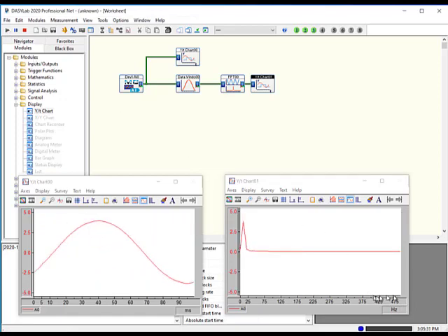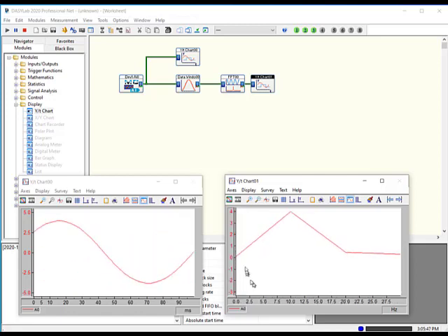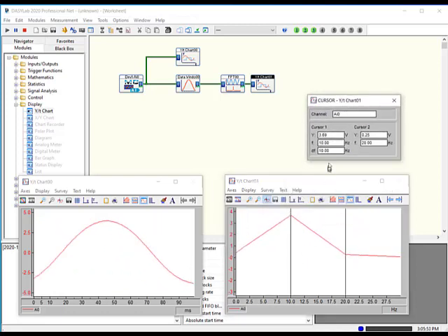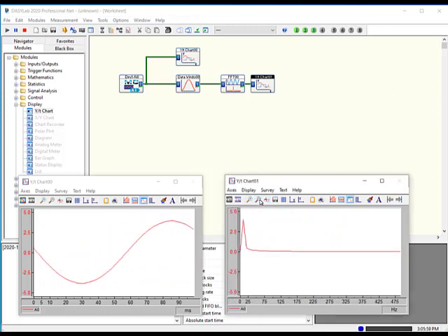and the x-axis on the second YT chart has been transformed from milliseconds to hertz. And so now that you can see, I've got a signal that's hanging there around 10. Well, that's actually pretty good for my little device. I'm going to turn on a cursor so that we can see, indeed, the frequency is 10 hertz. I'll turn the cursor off and unzoom and change the frequency.